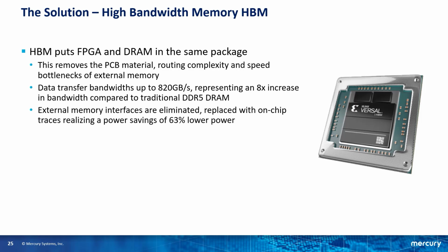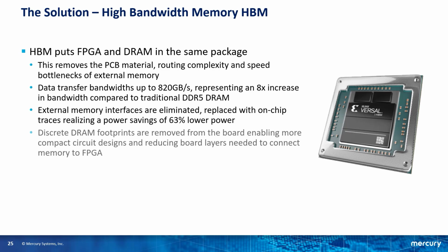External memory interfaces are eliminated, replaced with on-chip traces, realizing a power savings of 63% lower power. Discrete DRAM footprints are removed from the board, enabling more compact circuit designs and reducing board layers needed to connect memory to FPGAs, and that can lower the cost of the PCBs.